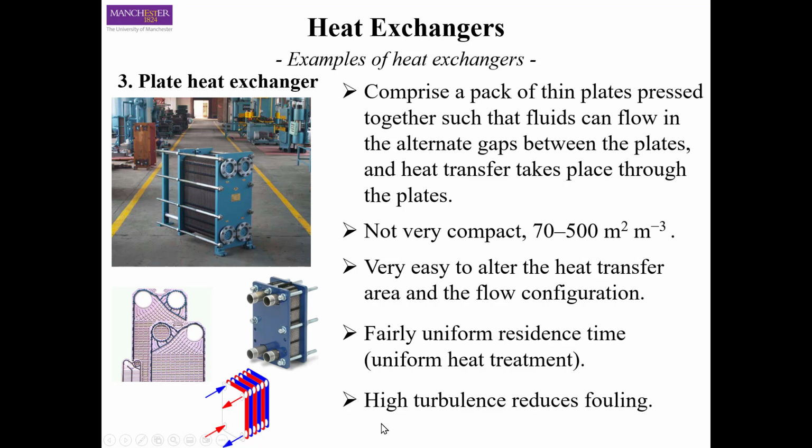And also, these heat exchangers have very high velocities of the liquid and a lot of turbulence, as you can see, with a lot of channels that create turbulence. That's why they have no fouling, and that's very important for heat transfer. And as we will see in the next lectures, fouling can affect the heat transfer.